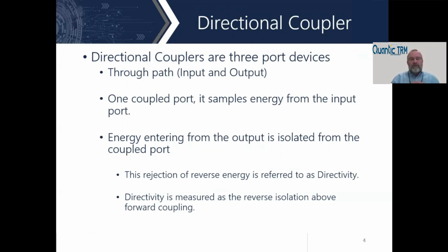So really, it's a 3-port device. Energy goes through in the forward direction, and a small part of that energy gets coupled back out to the coupled port. Energy flowing in the opposite direction gets rejected, and basically just goes straight through the unit.